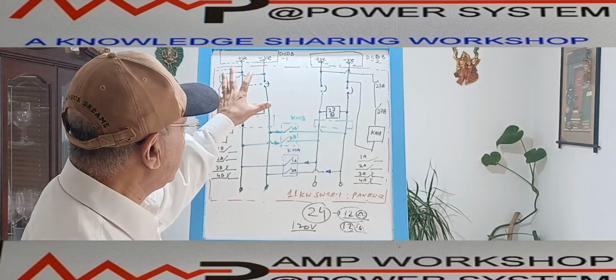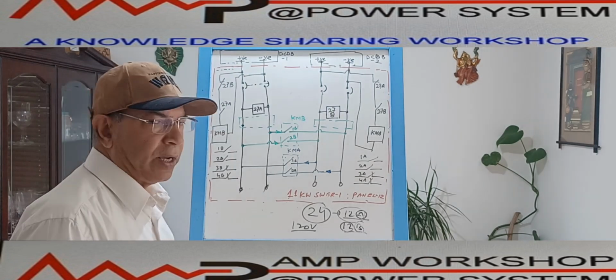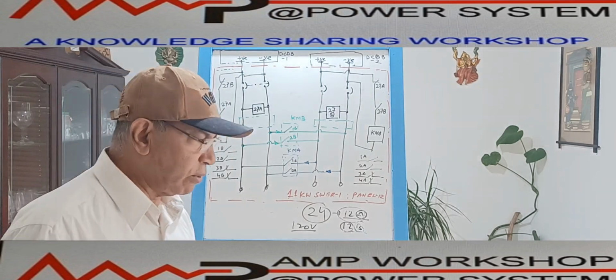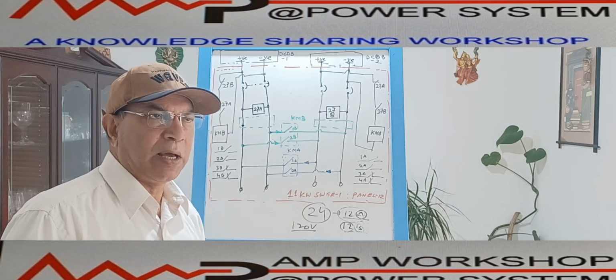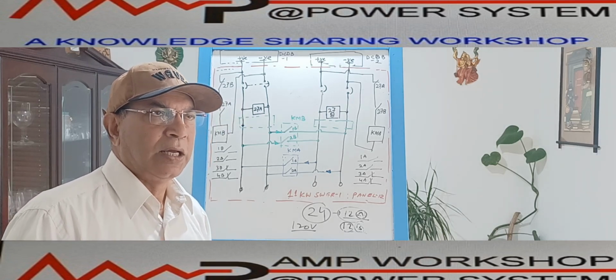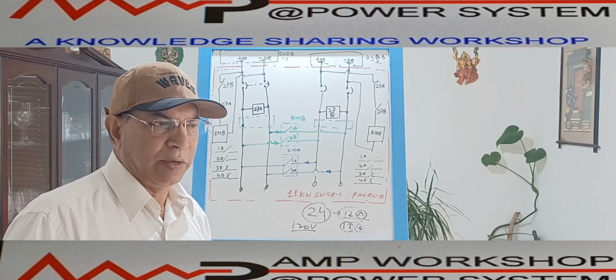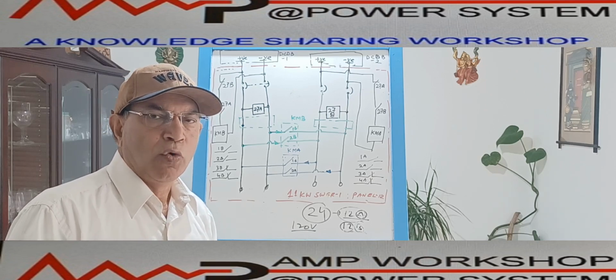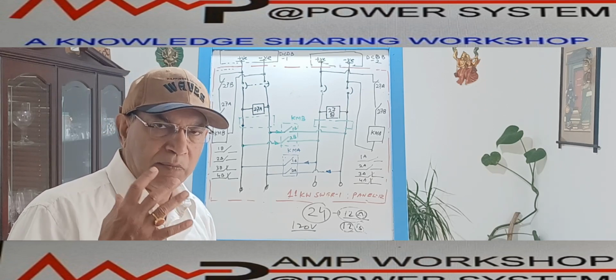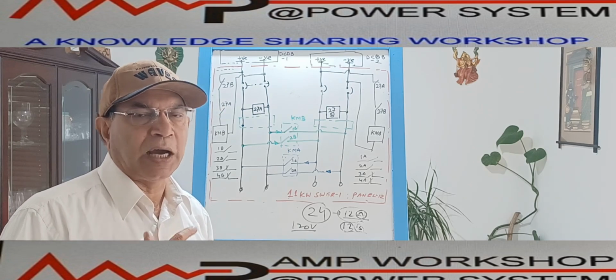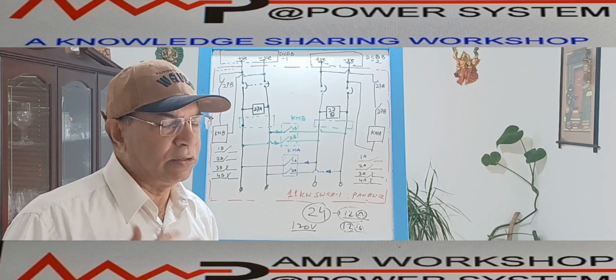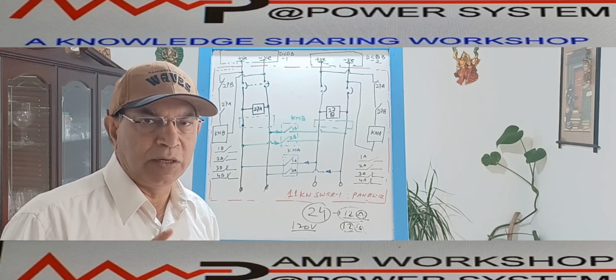Here we are first considering DC supply. Now here is one consideration: DC supply and AC auxiliary power supply have a slightly different arrangement for the changeover scheme. In the case of DC supply, we can connect same voltage level DC supplies directly without any synchronization. Synchronization is not required for the DC supply, you know that.